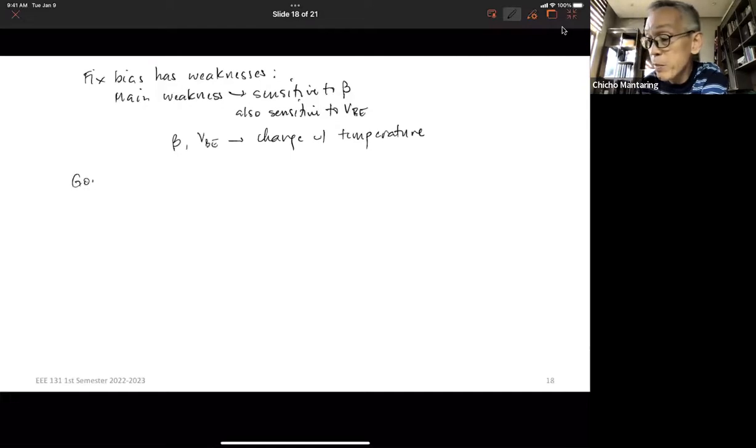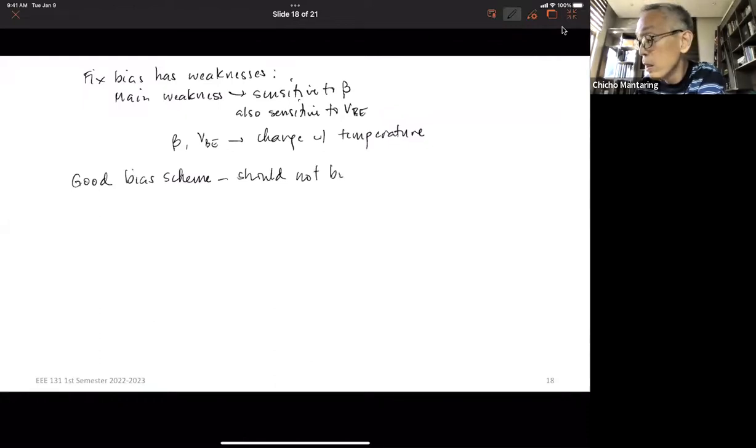So a good bias scheme should not be sensitive to beta. That's the most important. Okay. So I'm going to discuss with you in the next meeting some other possible bias schemes. So I'll stop there first.